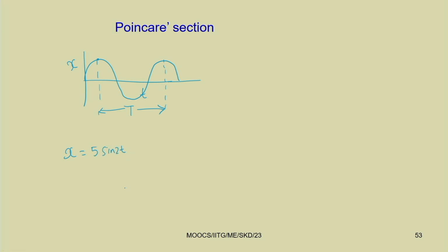2t. So, in this case omega equals 2, which implies the time period equals 2 pi by omega, that is 2 pi by 2. So, this becomes pi. So, the time period becomes pi seconds. In this way you know the time period. After you know the time period, this x versus time response plot you have plotted. So, how have you plotted?